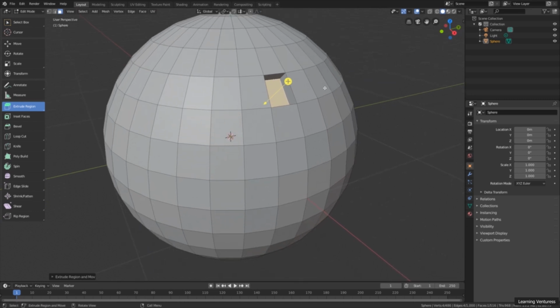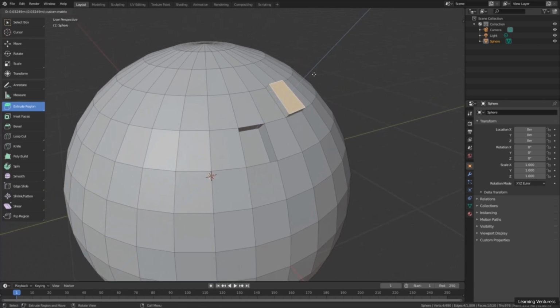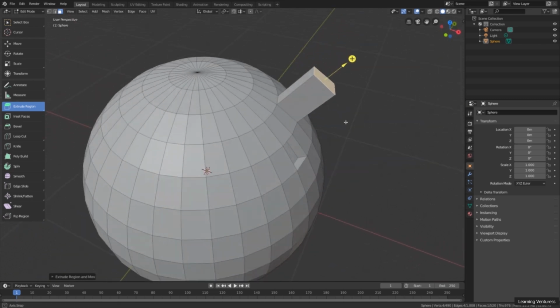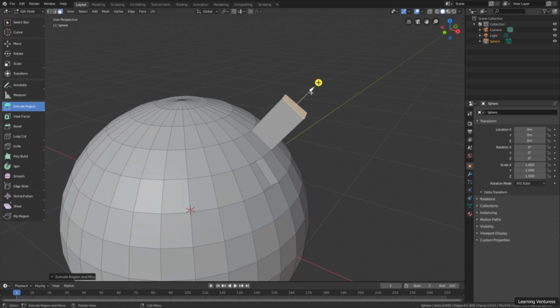And if we select a polygon and click on the plus icon and drag it out, we create a positive extrusion. Right after using the extrude, we can see that besides the plus icon, you can see an arrow in front of the face. If we click and drag on this arrow, we can reposition the polygon, adjust the size of the extrusion. And if we click on the plus icon again, we create a new extrusion with new polygons.